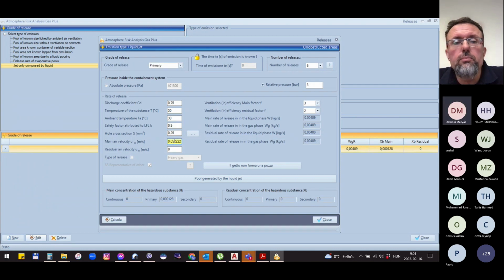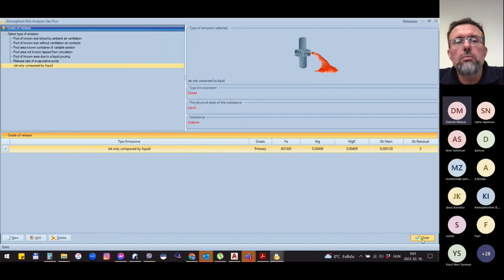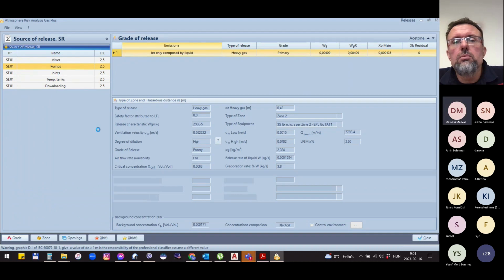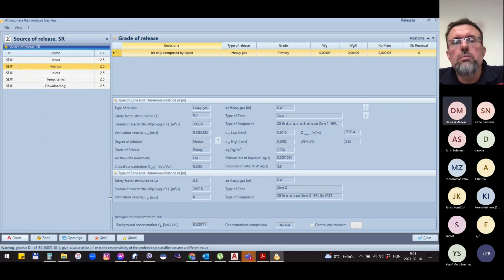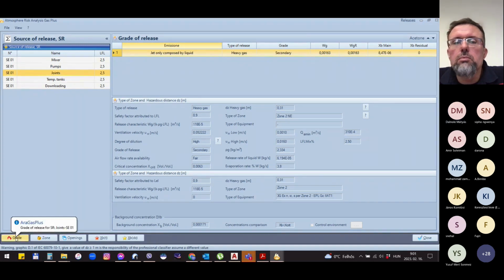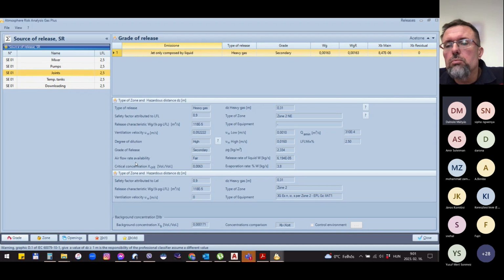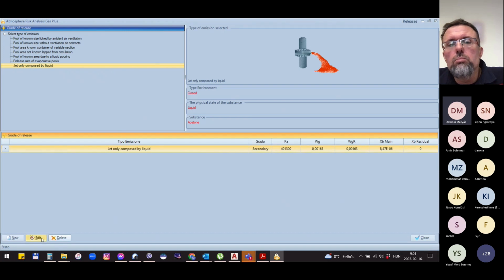Now I just would like to show you that if we wouldn't have 10 times air change rate, only 5 times air change rate, and I reduce the airspeed for all, it would be checked that here you can say now it appears zone 2 only for the second recalculation, because if we wouldn't have 10 times, only 5 times, it means that we reach the critical concentration earlier, maybe can reach.